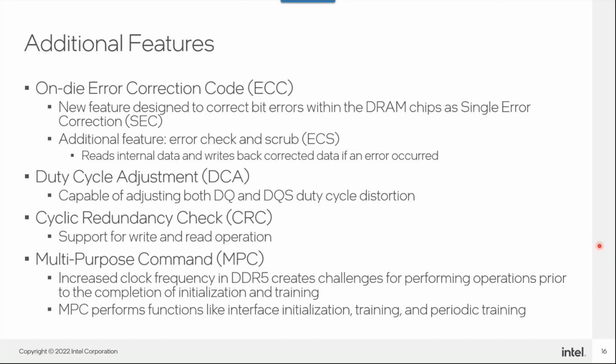And lastly, the multi-purpose command, MPC, performs functions like the interface initialization, training, and periodic training. On previous DDR DRAMs, these functions were individual commands or mode register settings. So now they're just in one command. And next slide, please.